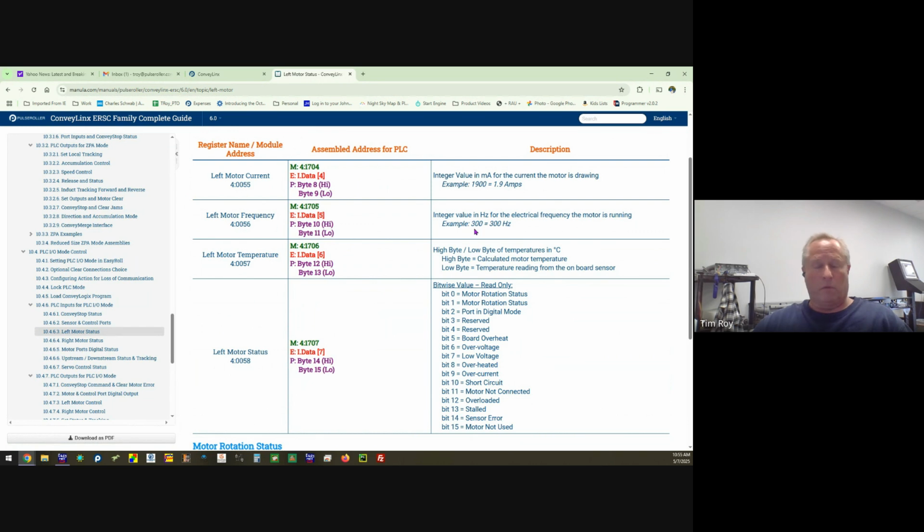If your motor is in eco mode, 483 hertz represents 100% speed. And it's not solid, it'll bounce. It may say 481 to 485, bouncing right there. If your motors are in boost or boost 8 mode, 100% speed would be represented by 350 hertz.